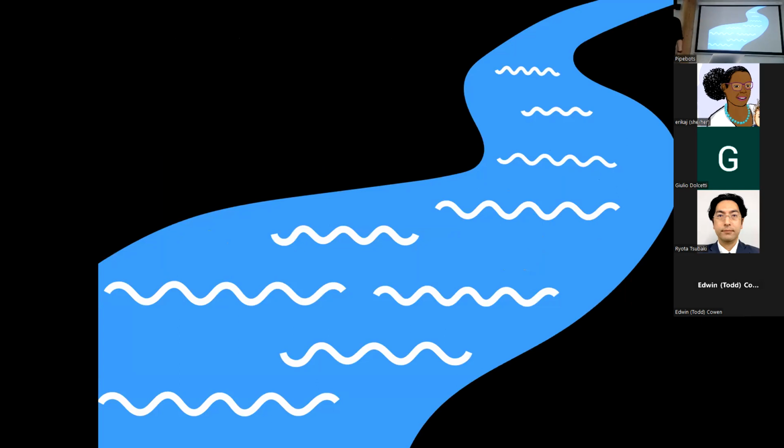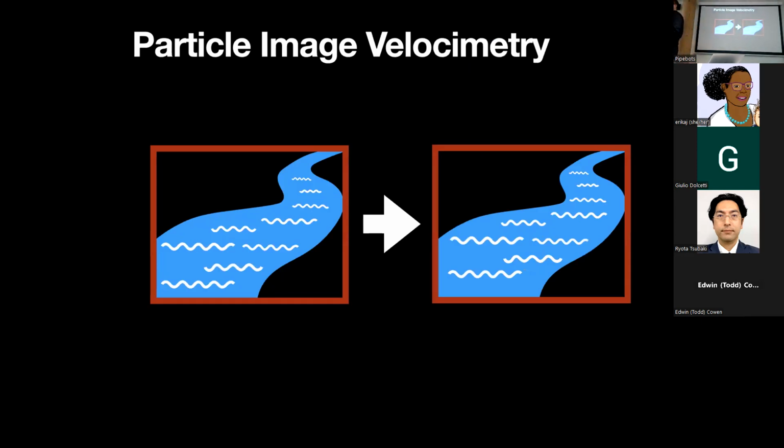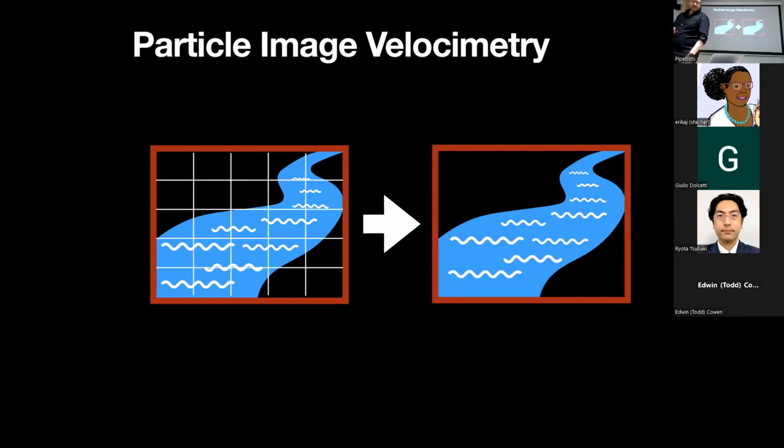Usually we've got something like this, so we've got some features on top. So often we'll say, right, let's go to particle image velocimetry. In a very simplistic way, we have two images slightly changing between the two. And we might say, well, let's grid it. So let's stick on some sort of grid. It might be adaptive, it might be moving, it might be circular if you love it. But you've got this grid, and I'm now going to stick it into some domain. Fourier domain is quite useful. Do a fast Fourier transform, and I can find that point. I'm going to find how it's displaced. That's particle image velocimetry in a nutshell.